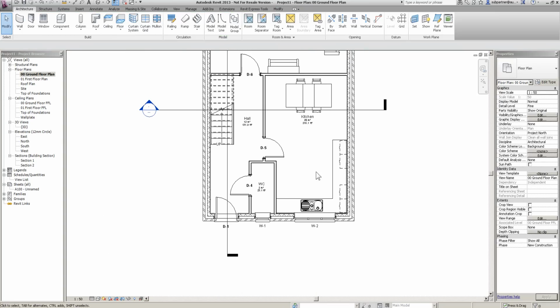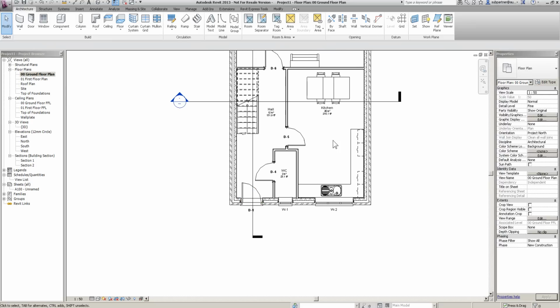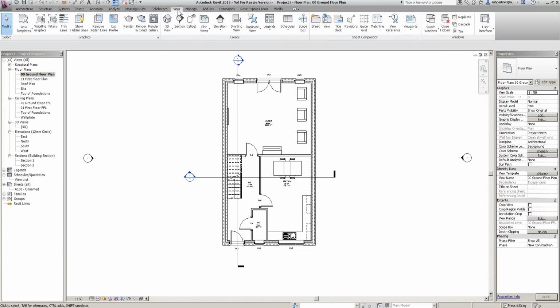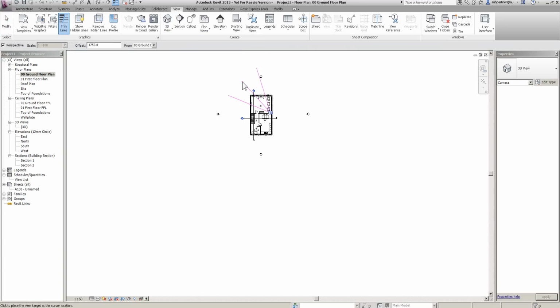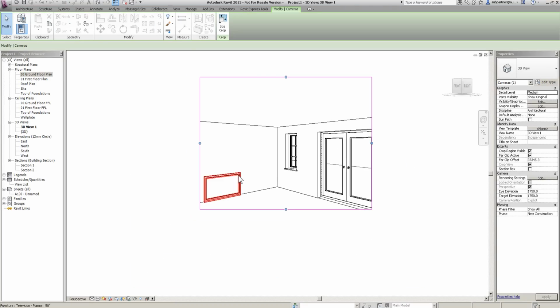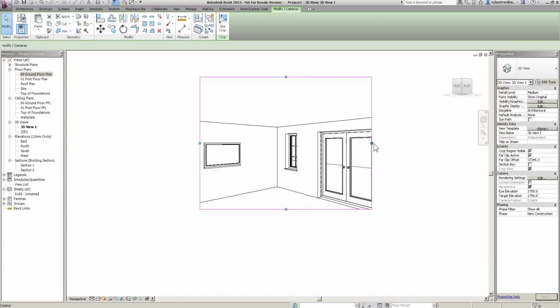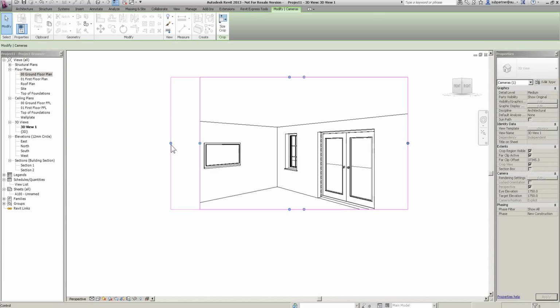Now what I'm going to do is place in here some cameras, because we haven't seen the cameras yet. So I'm going to go to either my quick access toolbar just here, or under your view tab just here, throw a camera in. I'm going to throw a camera in looking outside my building. Always take the focal point beyond the building. There we go. Schoolboy error again. Okay, it's on the floor. That's no good. Let's place it up just there. Fantastic. Once the camera's in, let's just drag this. Don't drag it too much because it will obscure it if you're not careful.